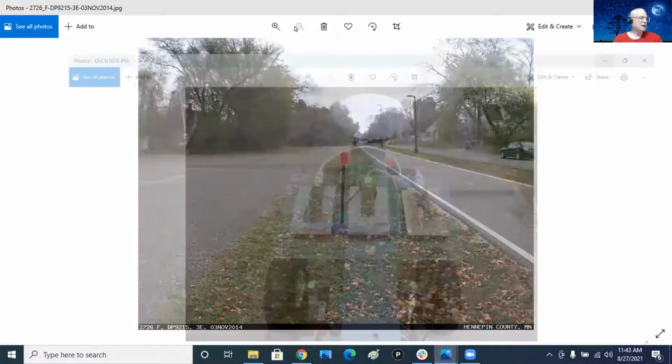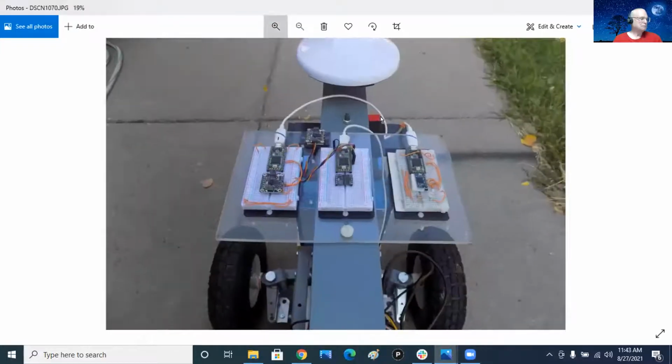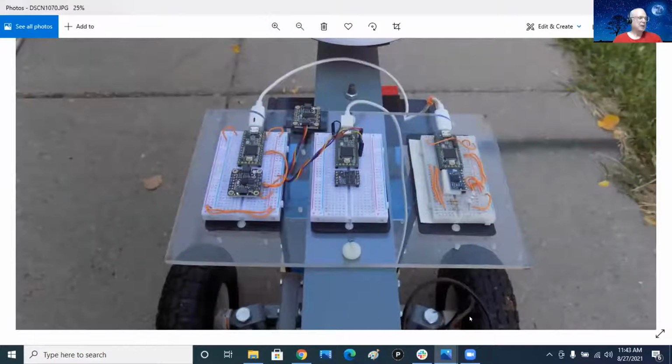This is my setup on the front of my robot. I've got this plastic plate, and there's three separate IMUs bolted down to it. The one on the right here is the BNO055. And the one on the left was my new BNO085. And I thought, hey, I've got another one laying around. So this one is actually that EM7180 chip that everybody was buying on Tindie. I simply unplugged that, and here's my second BNO085. I just got the wires plugged into that Teensy. So I've got 3 separate IMUs on this thing.